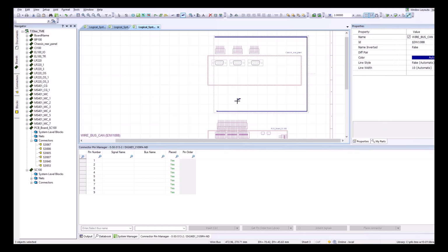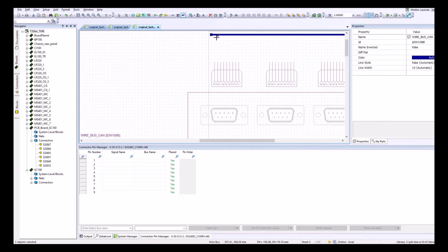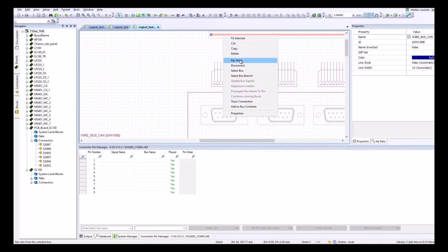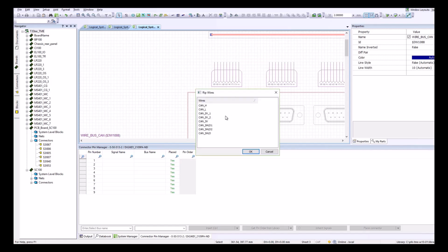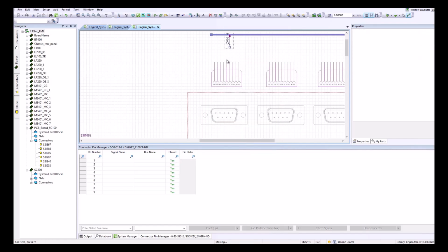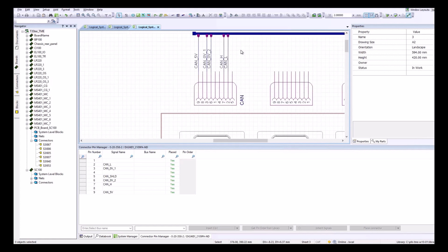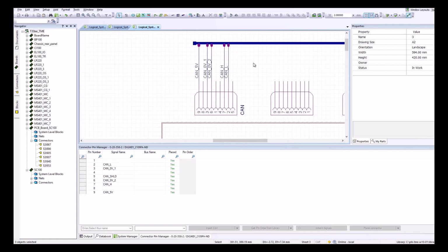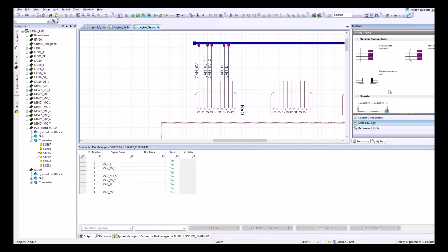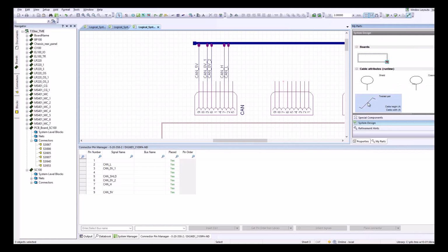And the wires can have a predefined bus content, as in this example. So the existing wires can simply be ripped from the predefined bus contents list that we see here. Once we've ripped these wires from the bus, we can go ahead and define any twisted pairs and/or shields for the cable. This is done by placing a special symbol type on top of the wire graphics in the schematic. This will create a multi-core wire structure in the cable assembly.